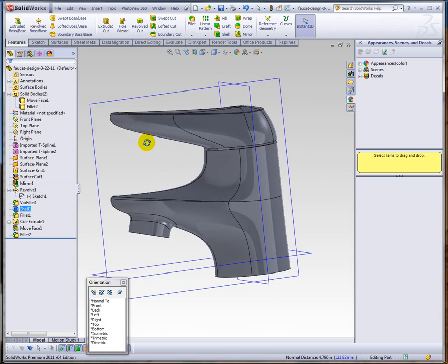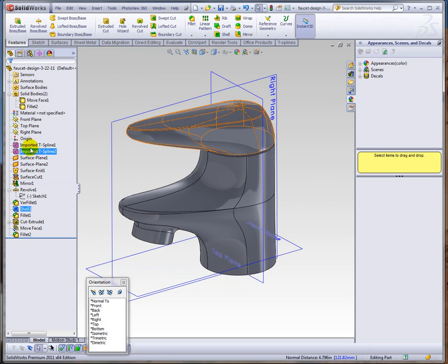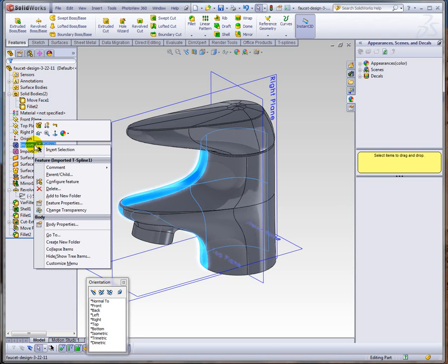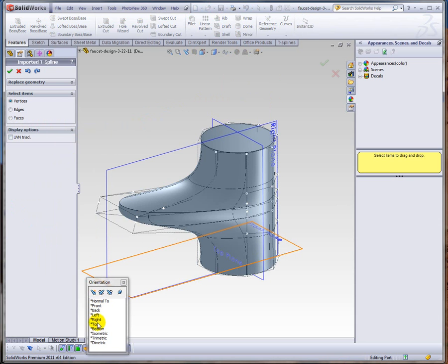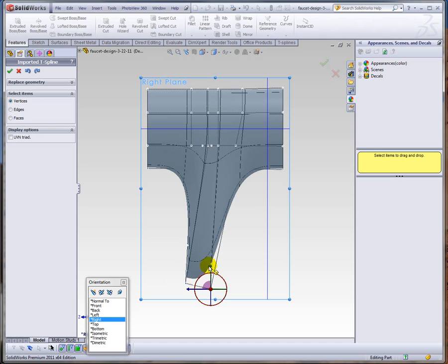So now what's interesting is that if we want to do any adjustments on this, we can do that by editing one or both of our T-Spline surfaces. So let's say for instance I actually wanted to do some adjustment here, and I'm going to pick our T-Spline here, and in my right view say I want to actually kind of pull down this area, bring it in a little bit more. I need more material at the end here.